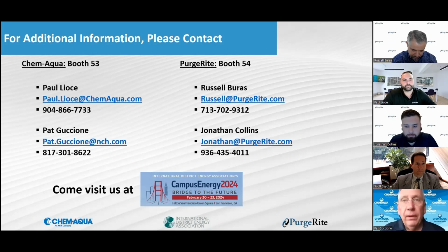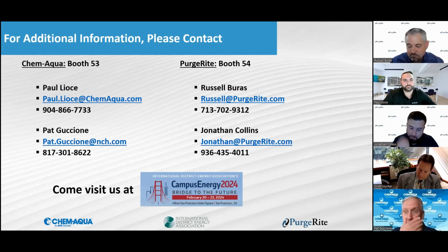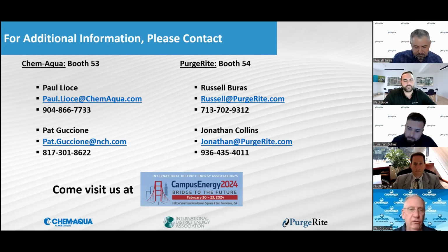Okay, let me jump in on that one. And let me say that if you have a fairly large system, several 100,000 gallons up to several million gallons, and you've lost control of your biology, it's very important to try and get it back. One of the things you're going to want to do is that for those purposes, the best biocide you can use is chlorine dioxide. And the reason you want to use chlorine dioxide is it's an oxidizing biocide, but it's not as aggressive toward your ferrous metallurgies as chlorine or hypochlorous acid or one of the other oxidizing biocides.